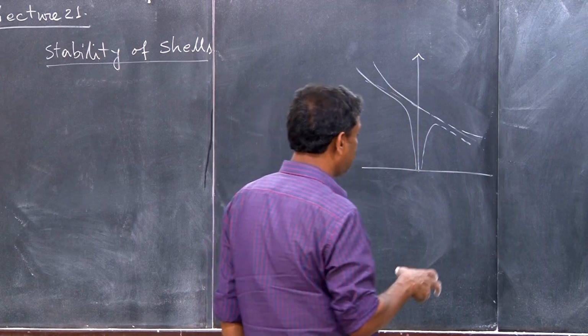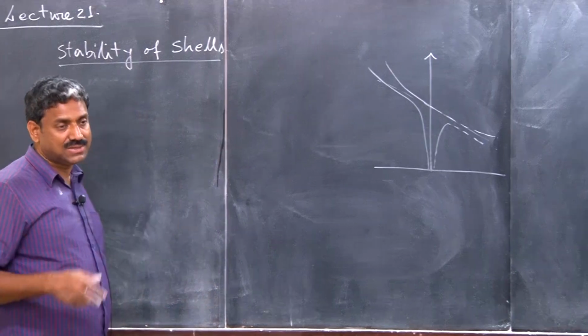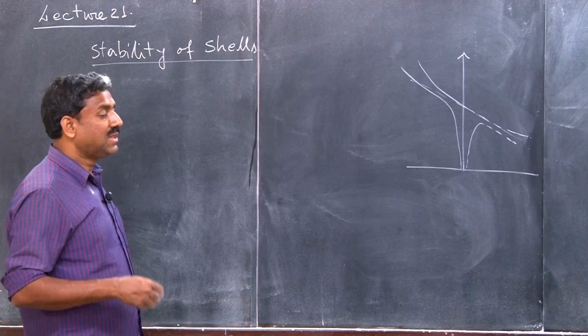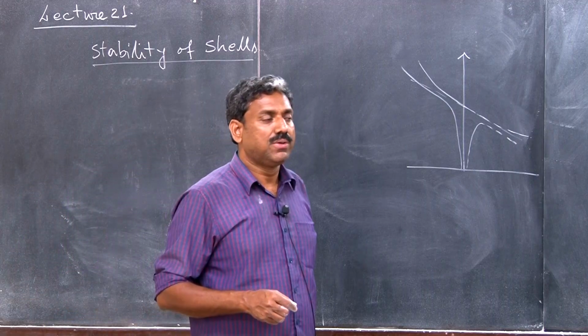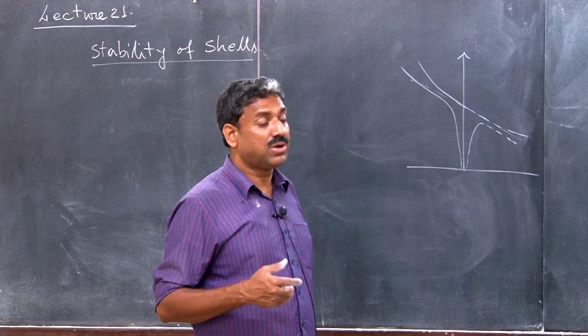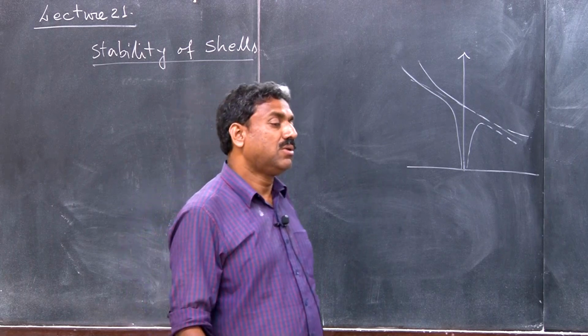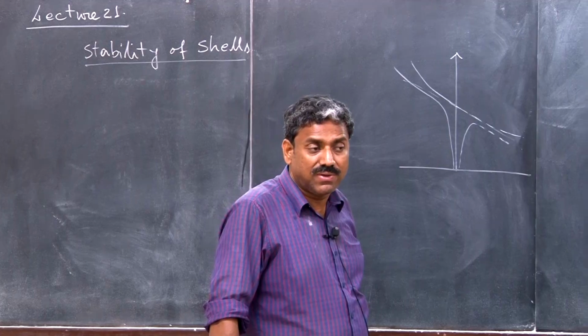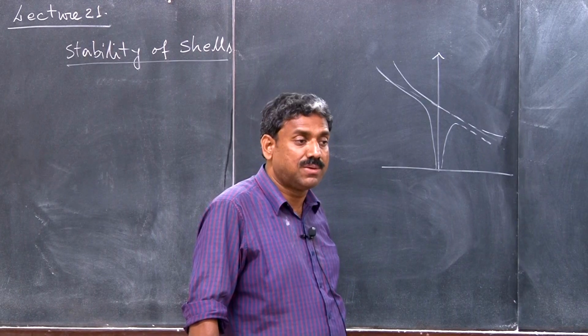All these cascading things have a cascading effect on the aggregate shell behavior, and that's why there is a huge drop in the critical load. This was initially not explained by the linearized shell theory developed at the time. None of them were able to explain the huge experimental drop that was observed in shells.